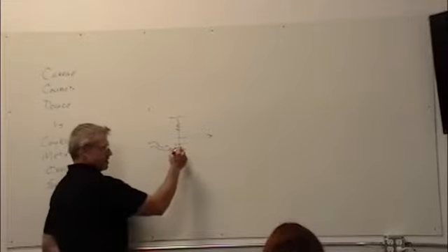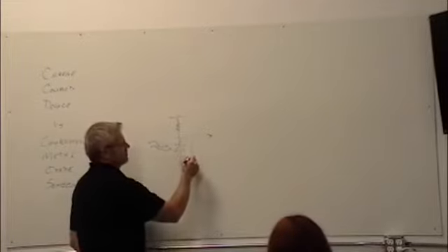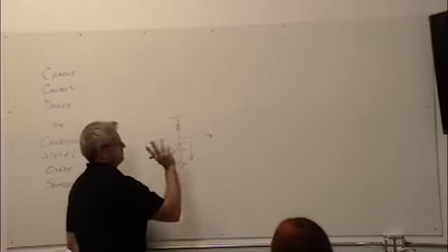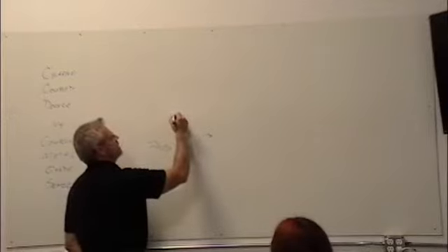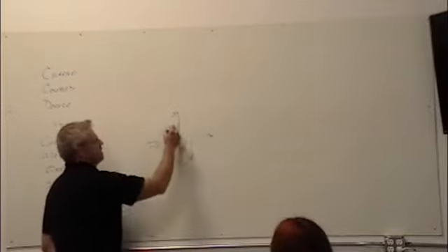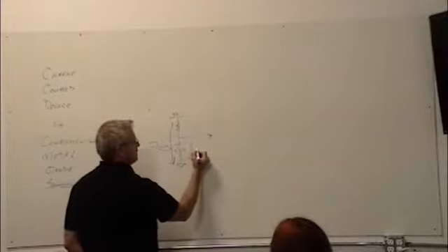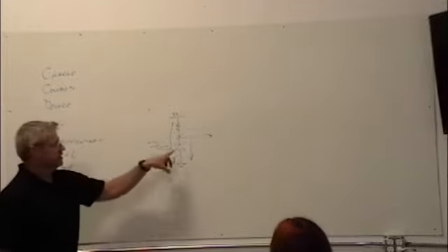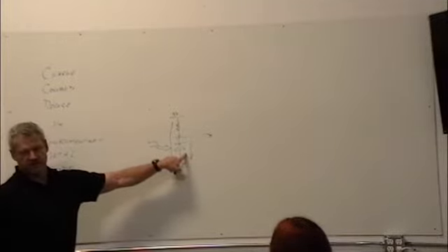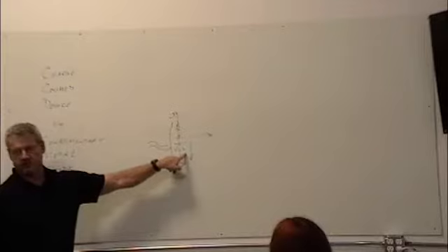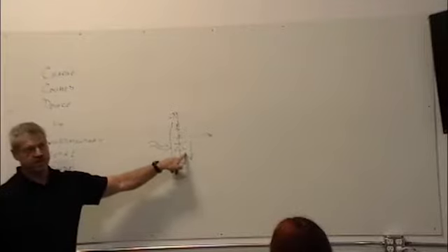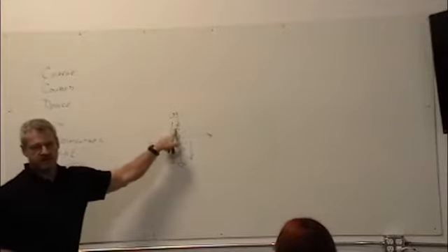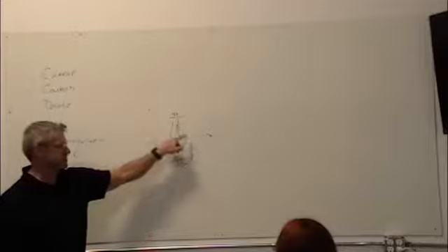Light comes in, electron-hole pairs happen, and it causes current flow through it. The P side becomes relatively positive, so if you have, say, a 5-volt rail up here, now I've got current flow coming through, and now I get a load drop there. This guy looks effectively infinite because he's not conducting much current. He looks like a current source. He looks like probably a 100 k ohm resistor sitting there.